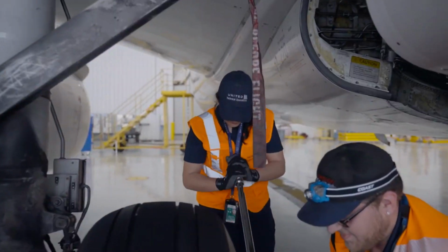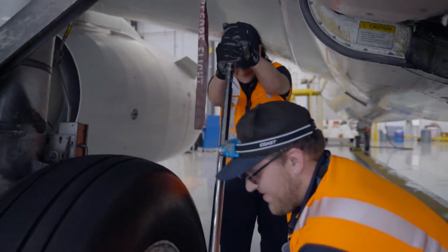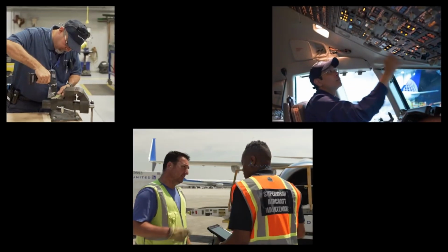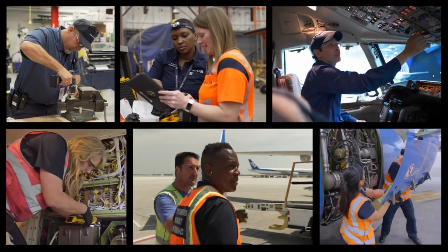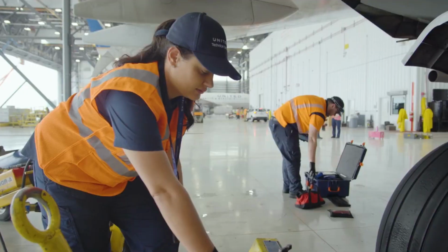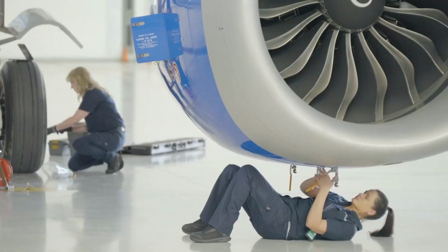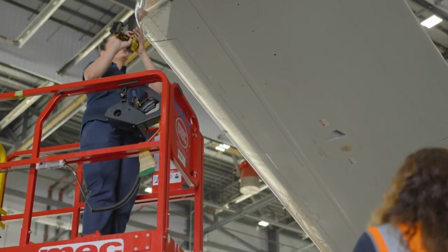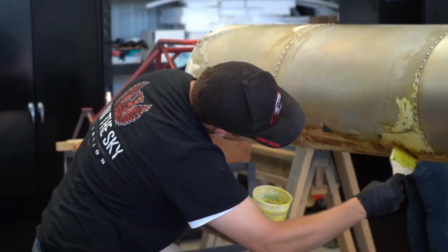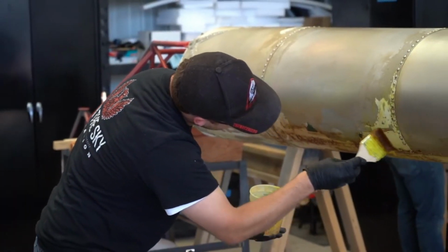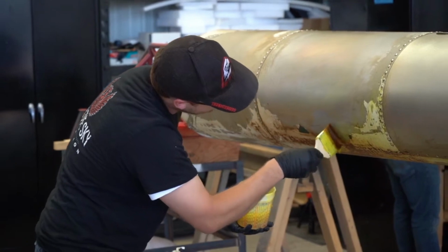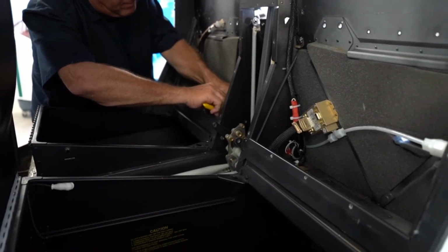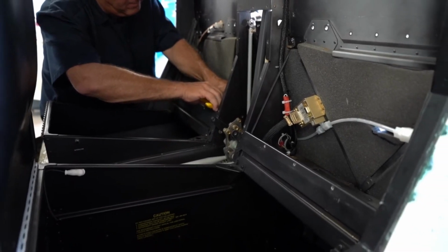If it is tested in accordance with approved standards acceptable to the administration that have been developed and documented by the manufacturer, the item is said to be overhauled. This is basically another way of describing service limits, a term frequently used to describe manufacturer-specified acceptable limits for used parts. A rebuilt item, on the other hand, must be tested to the same tolerances and limits as a new item. Section 43.3 Persons authorized to perform maintenance, preventive maintenance, rebuilding, and alterations.